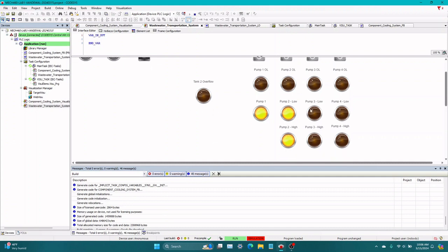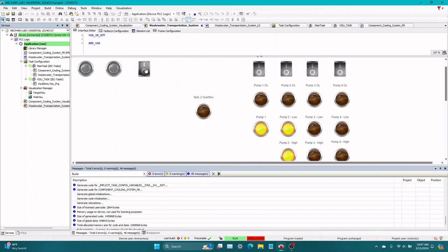After 15 more seconds, it will turn on pump 3 low speed, and then pump 3 high speed, pump 4 low, and pump 4 high. Those are all cascaded within 15 seconds. And it's set so that if this turns off at any time and it reaches the low level and comes back again, it resets.